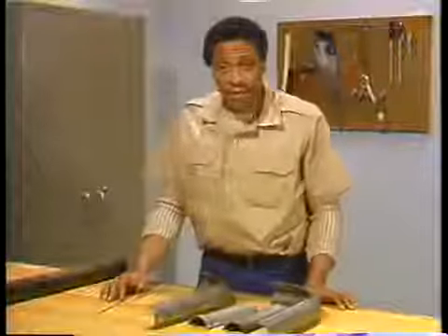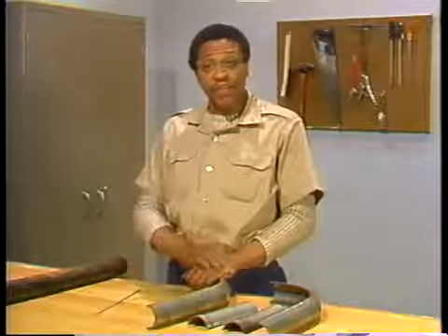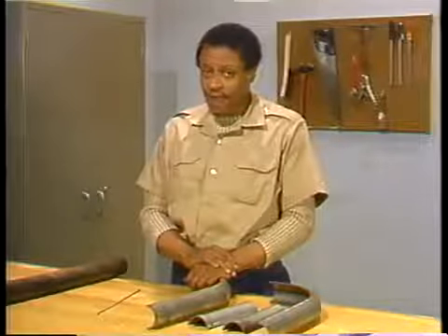As the patch is being applied, it is necessary to stop periodically to change the weld rod or to inspect the weld. Each time welding is stopped for any reason, slag must be removed from the weld with a slag hammer and wire brush before continuing. Also, the weld is inspected to see that the surface of the tube is covered properly and that the arc hasn't burned a hole through the tube.